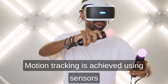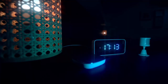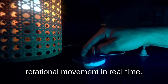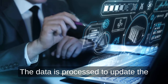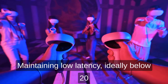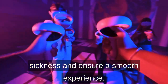Motion tracking is achieved using sensors such as gyroscopes, accelerometers, and magnetometers. These sensors measure orientation, acceleration, and rotational movement in real time. The data is processed to update the virtual environment instantly, ensuring low latency. Maintaining low latency, ideally below 20 milliseconds, is critical to prevent motion sickness and ensure a smooth experience.